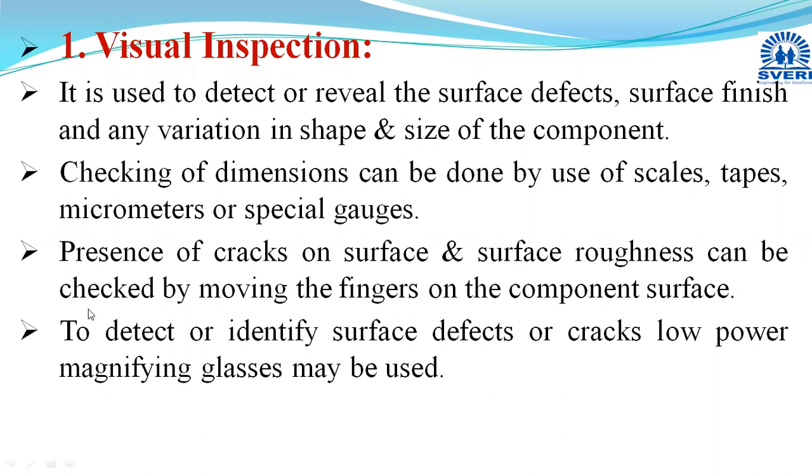And in some cases, for getting better results, we are using some magnifying glasses also, to detect or identify surface defects or surface cracks. We are using low power magnifying glasses to find out whether any kind of surface cracks or surface defects are there. So all these will be considered as visual inspection.